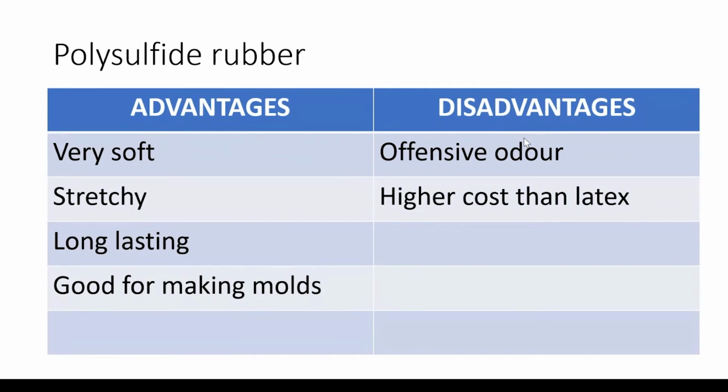And for the disadvantages of this kind of rubber, it has an offensive odor, and polysulfides must be mixed accurately by weight or they will not work. Polysulfide rubber costs higher than latex. Next.